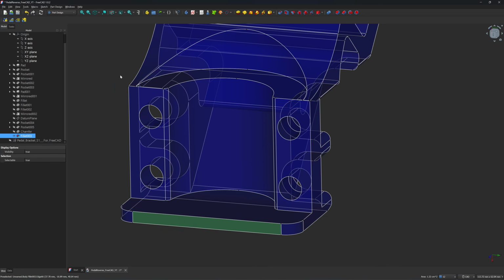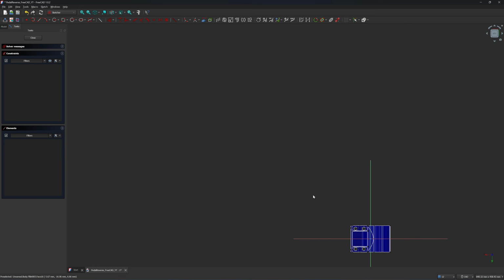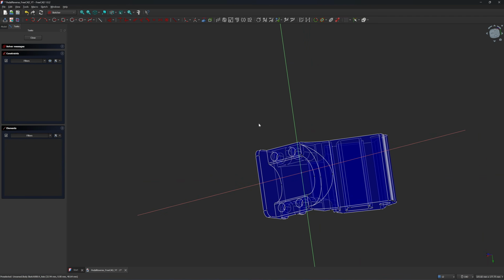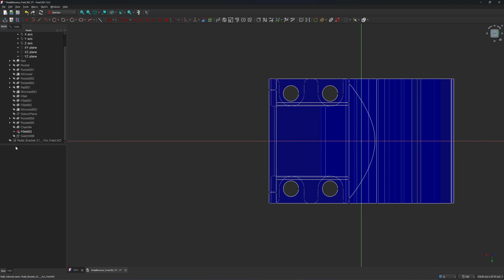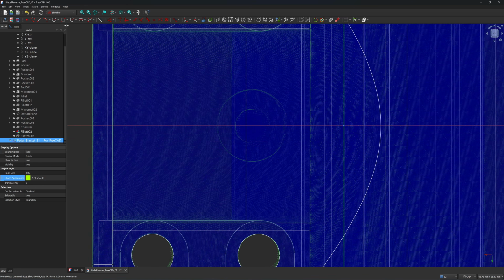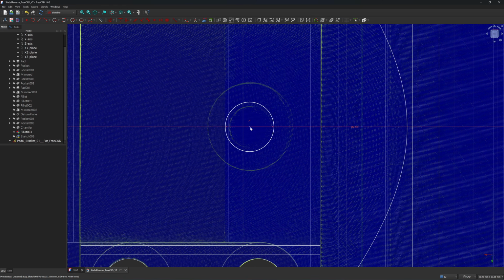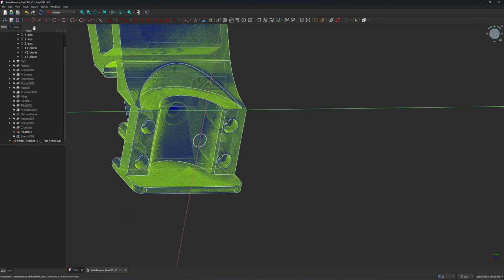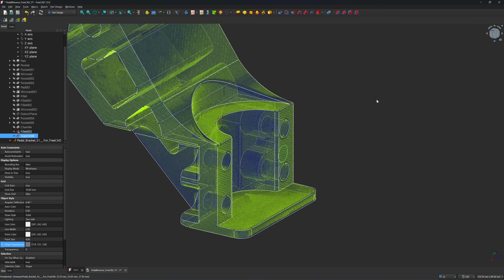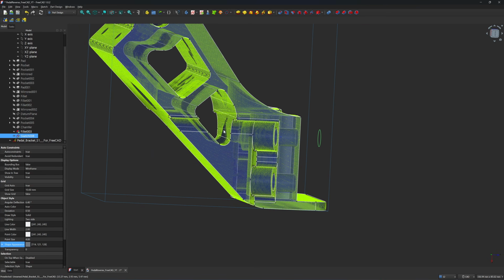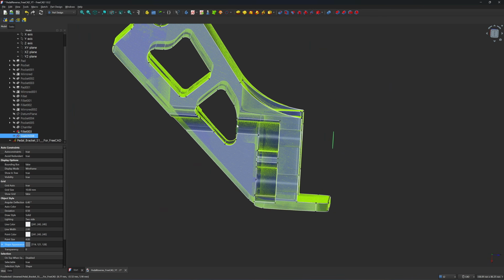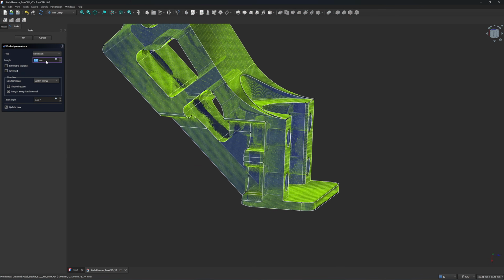First, click on here, click on create sketch. I'm going to create the sketch on this face. Turn the point cloud back on and create a hole, which for M6 will be 6 millimeter, and move it to the center. Then click on close, and cut it until it's just past this wall. So you're going to add the number.